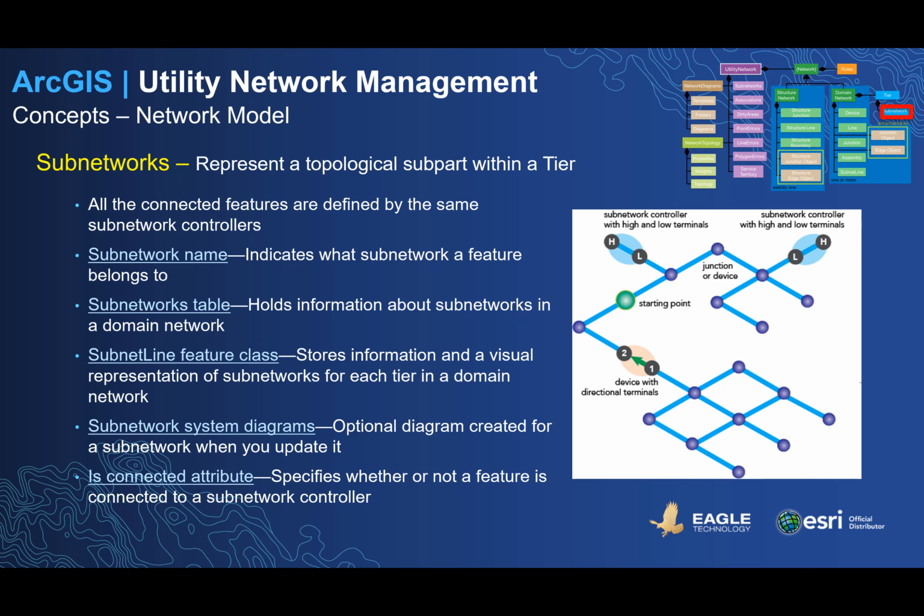Subnetwork system diagrams can be optionally created when the subnetwork lines are updated. And there's a system managed field in your domain features which you can specify whether a feature participates in the subnetwork based on its connectivity or lifecycle status.